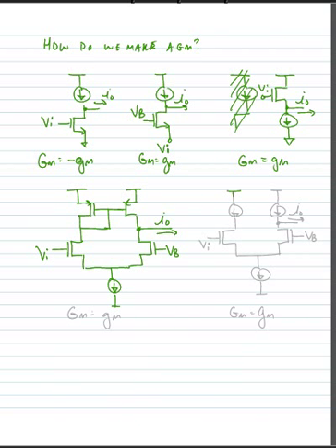We could also use current source loads in a very similar configuration. We connect one side of the differential pair to a DC voltage VB, put our input voltage in on the other side, and take a current I out from the opposite side of the device.